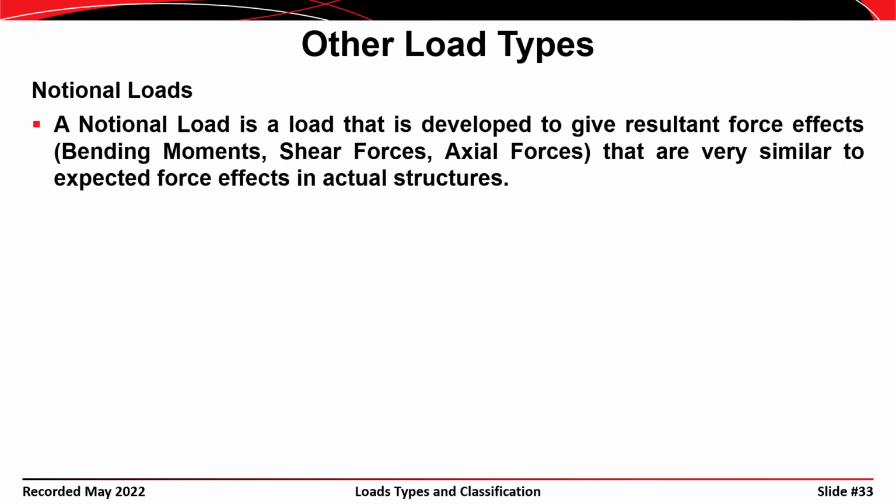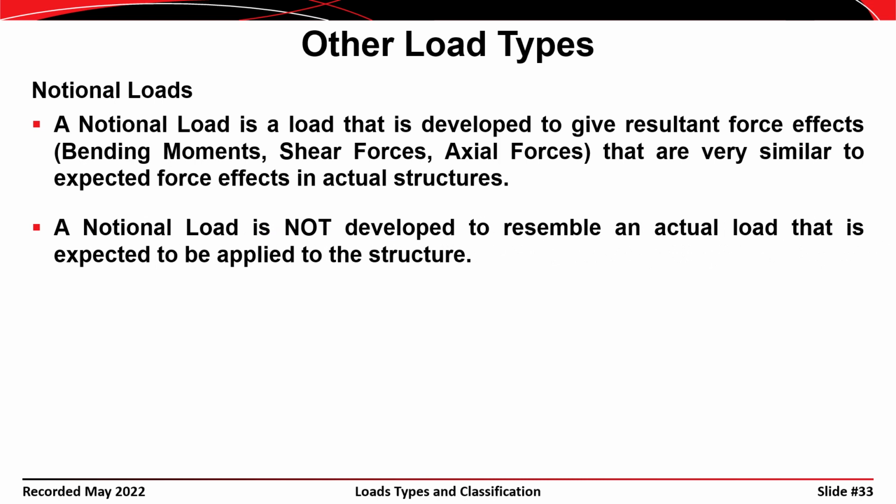Okay, finally, I promised to define what a notional load is. Notional loads are loads that are used to represent force effects that are important in the structure but aren't modeled explicitly. Notional loads are not developed to resemble an actual load in the structure. So as an example, we have to consider differential settlements in the design of our buildings, but modeling a settlement of a foundation is challenging in a lot of different aspects.